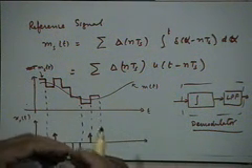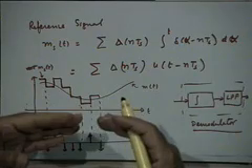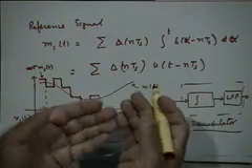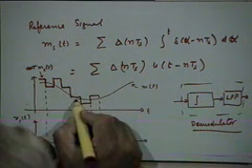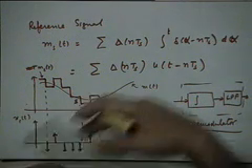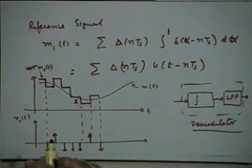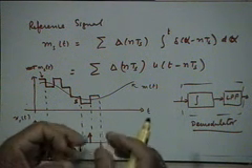Now there can be a situation that this staircase approximation is not able to track the rapid changes that are happening in the message signal. Every t sub s seconds, you are increasing or decreasing this staircase approximation by a step size. Let's call it s. Okay? You are increasing this value by s. So suppose your signal was only increasing, let's just for the sake of discussion, at a certain rate. What is the maximum rate at which the staircase approximation can attempt to follow that rise? Maximum slope of this rise would be s by ts, right?